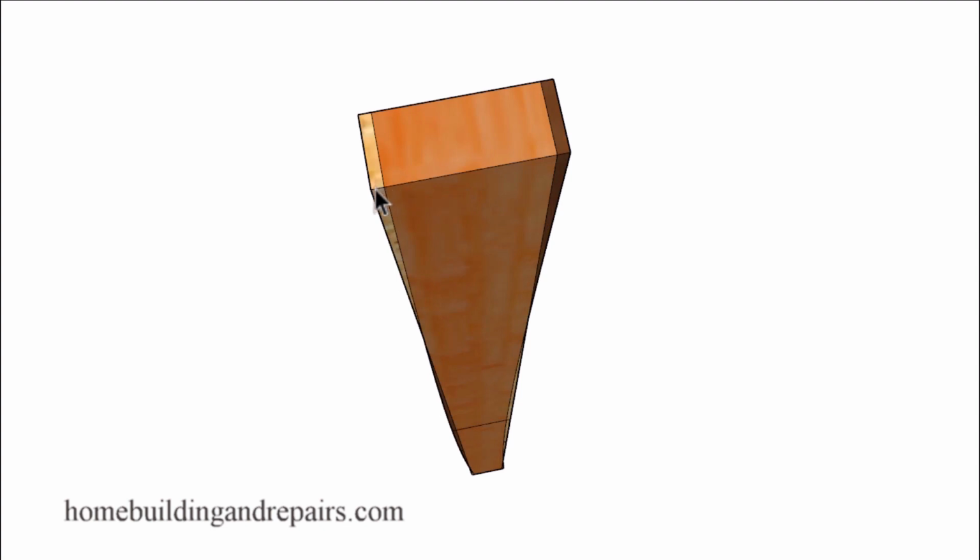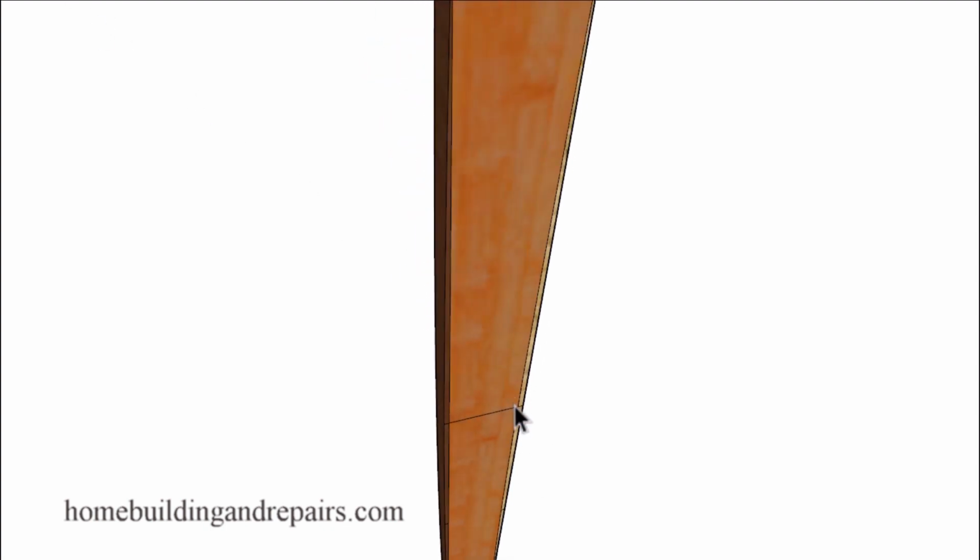If you simply move the wall framing stud over at the top a little bit. So in our example here, I moved it over 1/4 of an inch, and the wall framing stud has a 1/2 inch bow in the center. So again, we're going to be adding here, removing over here, adding on this side, and then doing the same that we did up here at the bottom. And it's going to provide us with a little stronger stud. So instead of having a wall framing stud where we've removed a 1/2 inch on one side, we're only going to remove 1/4 of an inch on that side.